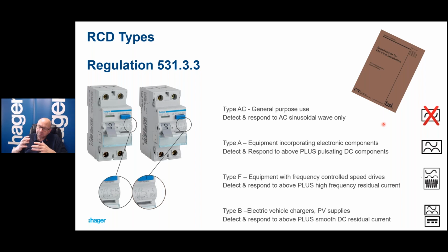It's widely known now. We call it blinding, some people call it masking, but you need to be careful, and some installations will actually specify a particular type of RCD to be used. But because of Amendment 2, we don't really see type AC devices as general purpose anymore.